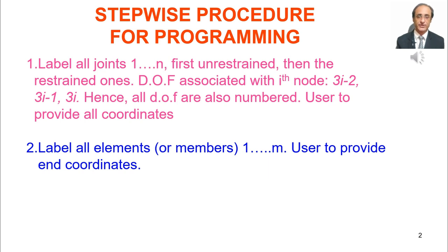User has to provide the near joint number and the far joint number, because these two joints, which is the near joint and which is the far joint, will define the coordinate system. If the two are chosen differently, we'll have different coordinate system. If the near and the far joints are chosen the other way, the coordinate system will also be different. This will be further clarified in the last slide of today's class, where a question from a previous year's student is addressed.